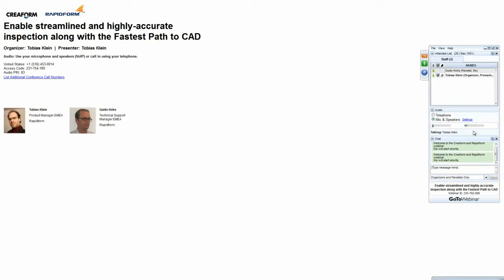Are all of these probings taken manually, or if I have a CNC run CMM, can they be taken automatically with that? Actually, we can virtually read any point cloud data format and inspect it against CAD, but the demonstrated method is designed for articulated arms or for tracked probes.